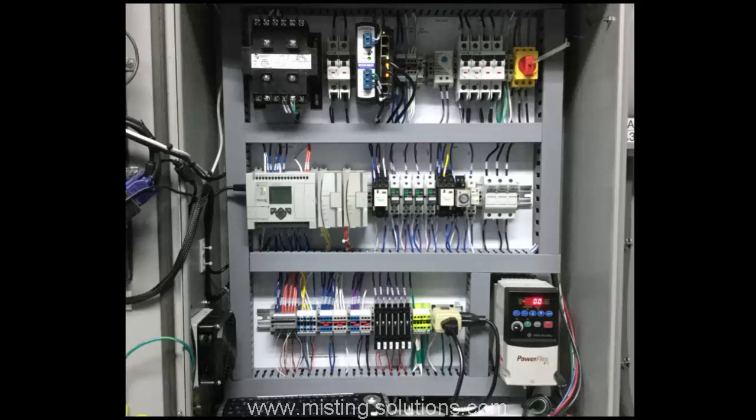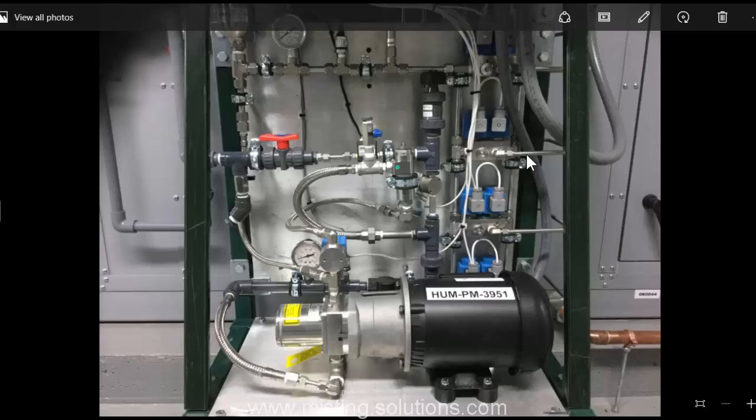So it's really a safety feature. When this last zone valve right here shuts off, there is high pressure water that is trapped in this line right here back to the discharge side of the pump and the check valve. Everything else has been dumped. All zones have been dumped except for this water that's trapped in here when the pump shuts off.